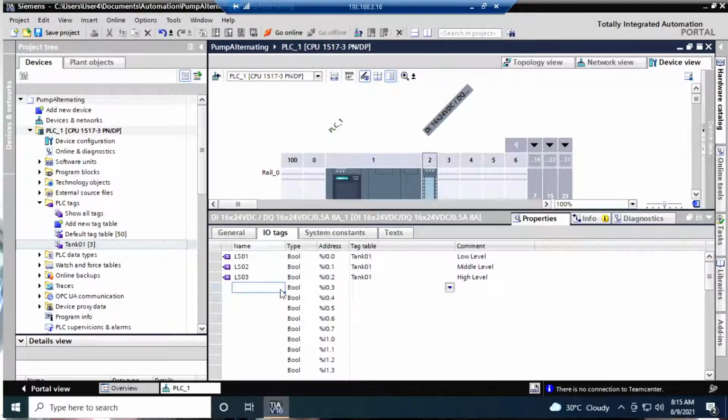We do want to take the motor running feedback. Even though we used the motor output for the programming, in a real situation you cannot use the output in your program. That's not the right thing to do. In usual practice, the contactor will have a feedback from the motor. When the pump is running, you get the pump feedback from the contactor. So you get something like pump 1 feedback and M2 feedback.